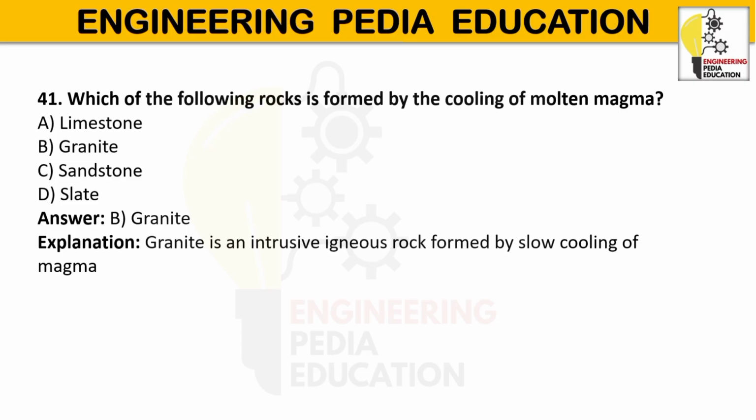Main minerals are quartz, feldspar and mica. Its color is grey, pink, red, black or white. Properties: very hard and durable, high compressive strength, low porosity and water absorption, resistance to weathering, can be polished to a good finish. Uses are building stone, flooring, wall cladding, bridges, dams, monuments and decorative work, road aggregate. Granite does not have a definite cleavage. It breaks by irregular fracture.